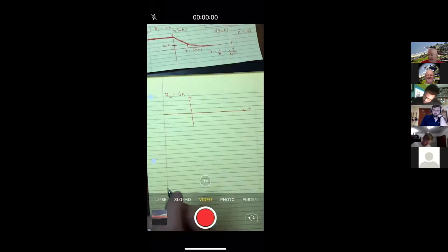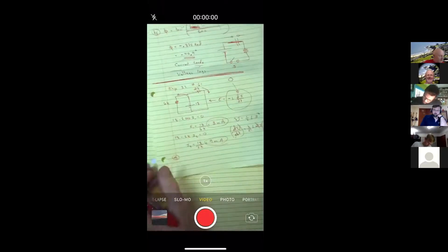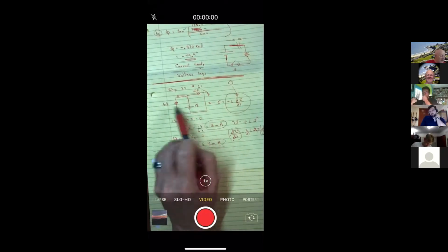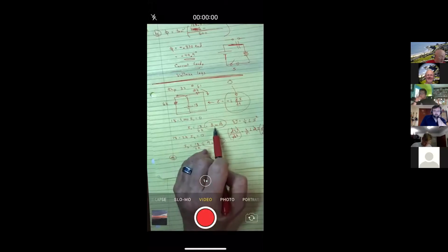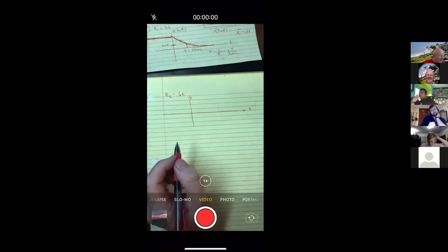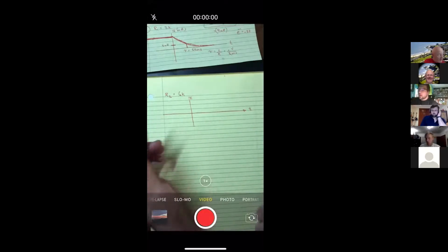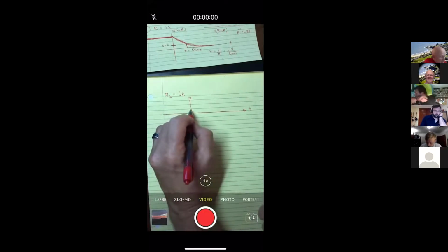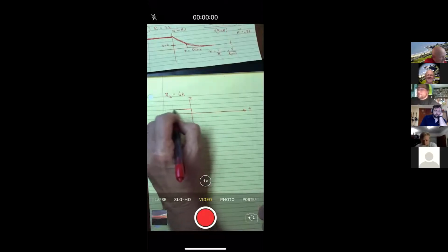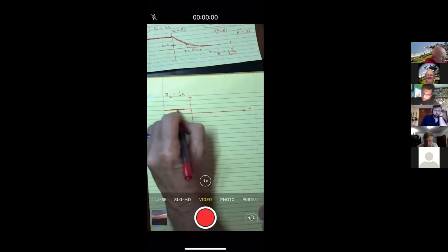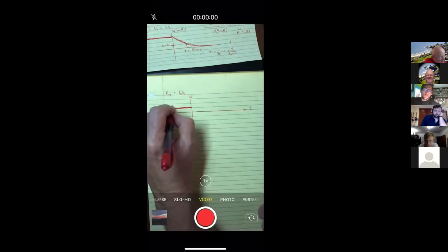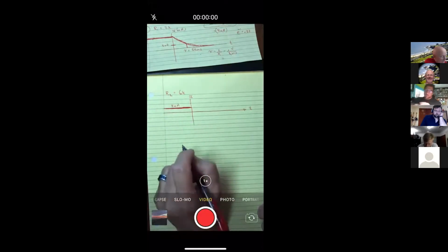Now, way back at the beginning of this problem, for this left-hand side, we said the steady state was 18 divided by 6. So we got the 3 milliamps. And the problem said, treat that as positive, the direction it was going in steady state. So if I use each division as 3 again, this is what it would be doing for times less than 0. We would be at 3 milliamps.